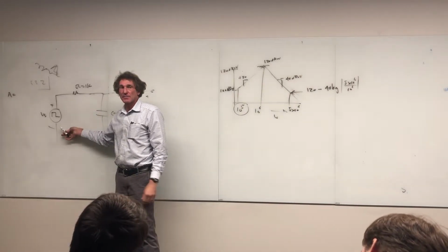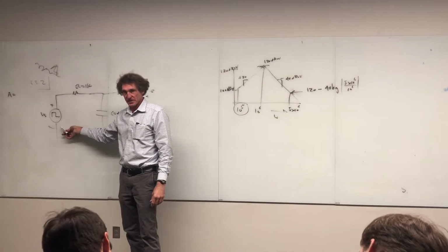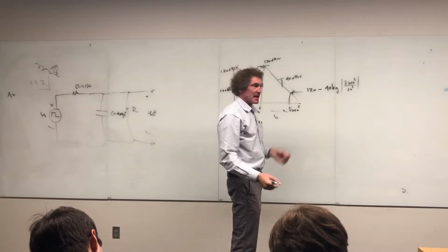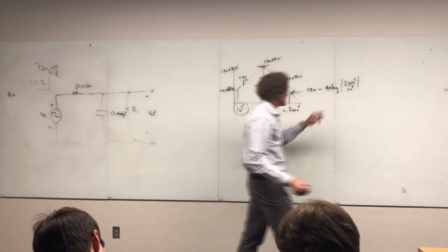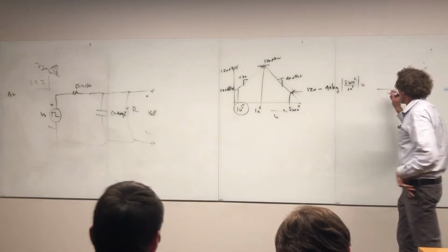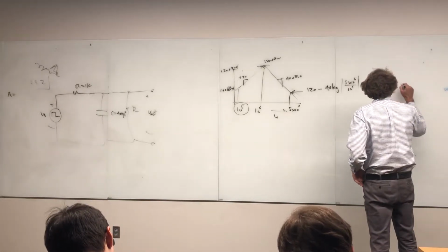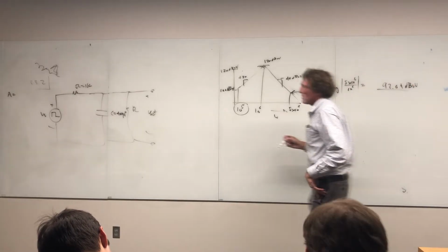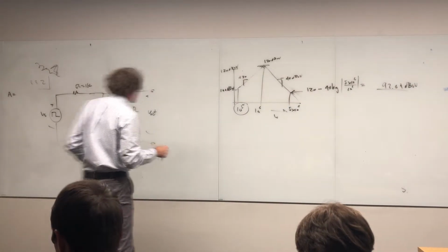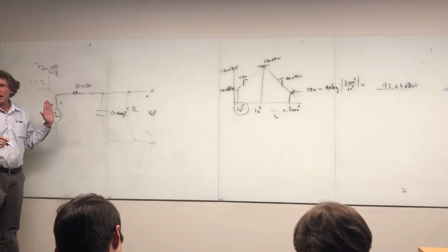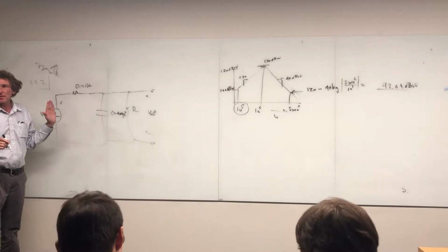Now that's the signal level right here at the source. We haven't taken into account the filter. I want to make sure you see every part of this. Got it, guys? So for whatever harmonic that is, the 50th, this is going to be the level. Just give me this value right here. 92.04. All right, 92.04 dB microvolts is what's coming at the 50th harmonic right here. That's the signal level, right? Now you have to account for what the filter does. Does everybody follow me?